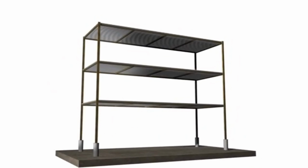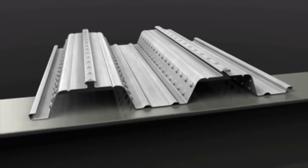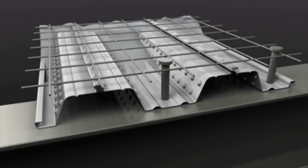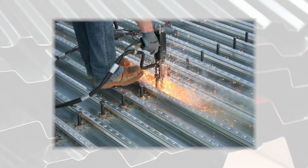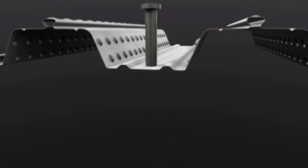The composition for the slab is usually a universal beam at which the metal decking rests, a reinforcement mesh for the slab, and then finally the concrete. And the metal decking has to be connected with the universal beam using what's known as shear studs that look like bolts.